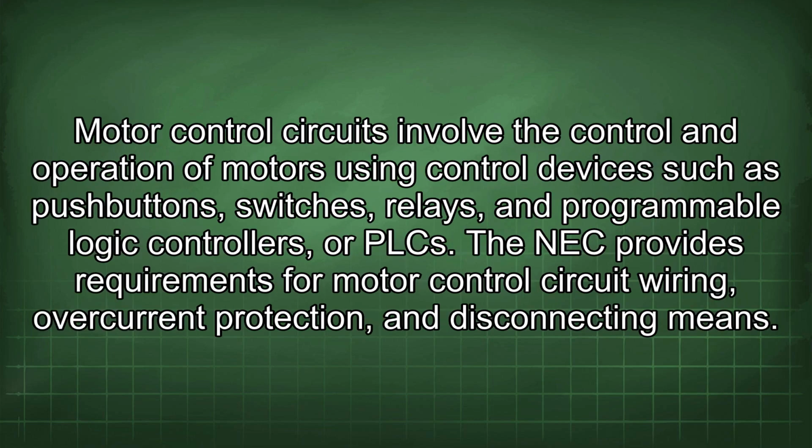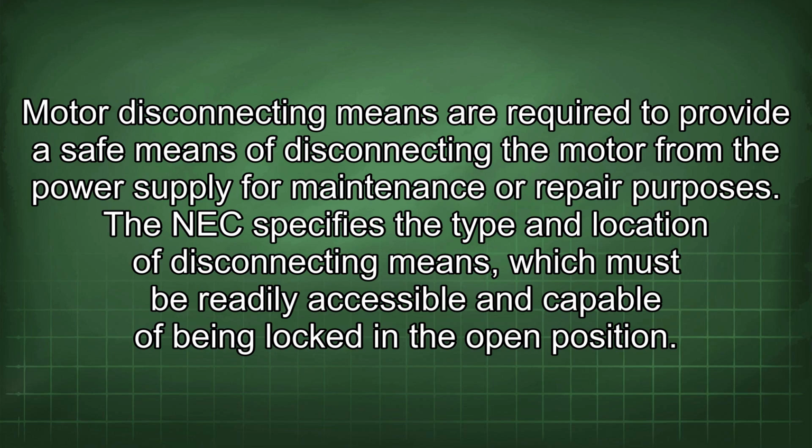Motor control circuits involve the control and operation of motors using control devices such as push-button switches, relays, and programmable logic controllers, or PLCs. The NEC provides requirements for motor control circuit wiring, overcurrent protection, and disconnecting means. Motor disconnecting means are required to provide a safe means of disconnecting the motor from the power supply for maintenance or repair purposes. The NEC specifies the type and location of disconnecting means, which must be readily accessible and capable of being locked in the open position.